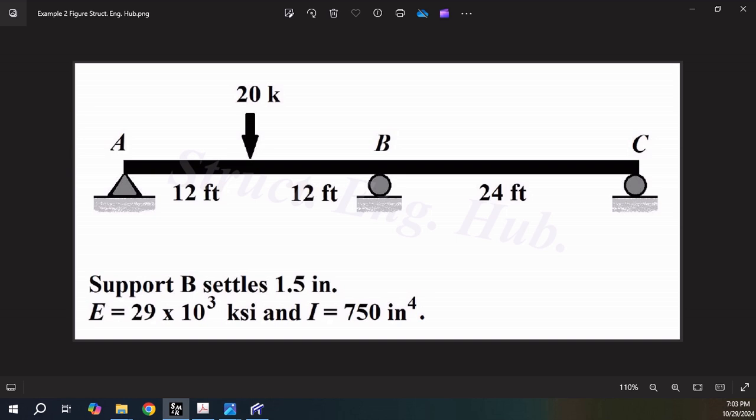The support at A is a pin, while supports at B and C are rollers. It is given to us in the question that support B settles by 1.5 inches. This means that there will be a vertical displacement at point B directed downwards. Also given to us in the question are the modulus of elasticity, which is 29 times 10 to the 3 ksi, and the moment of inertia of the beam, which is 750 inches to the 4.